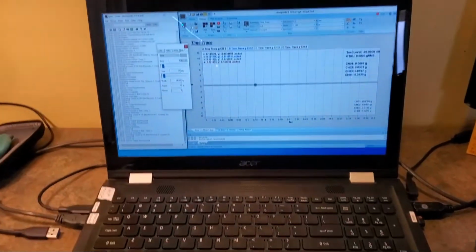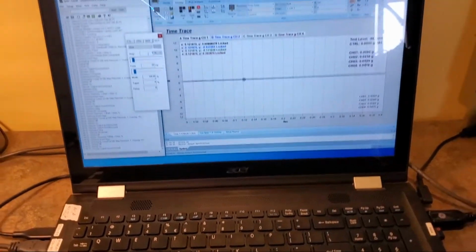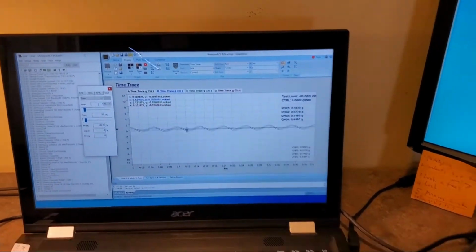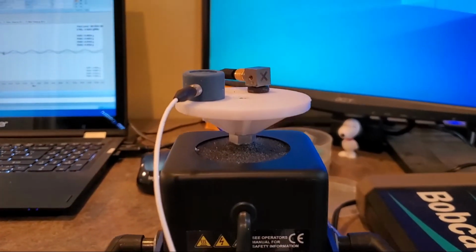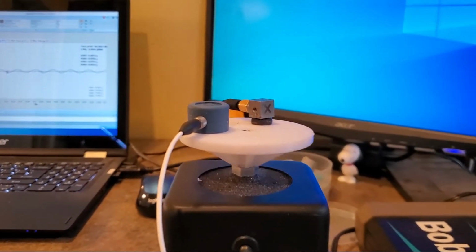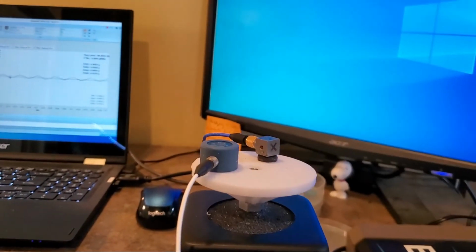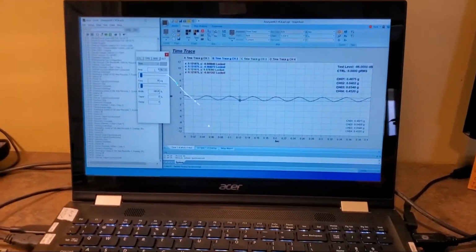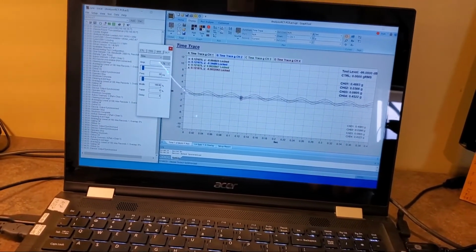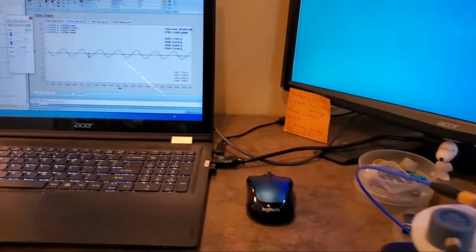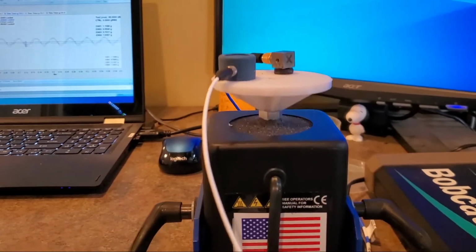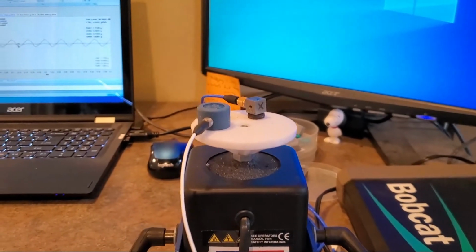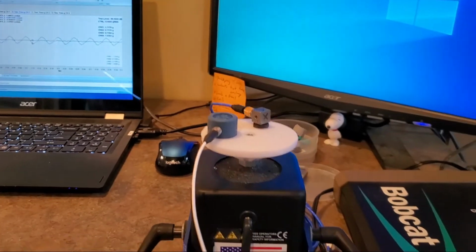All right. Next, let's turn the shaker on here. So we're going to turn this on. So you can see that we're measuring a sine wave there. Over here on the shaker, you can see some motion, a little bit there. You can feel it. So that motion is being measured over here. So what we can do is make that a little bigger. So come over here, and you can definitely see we are driving that system there and measuring it with the accelerometers on top.